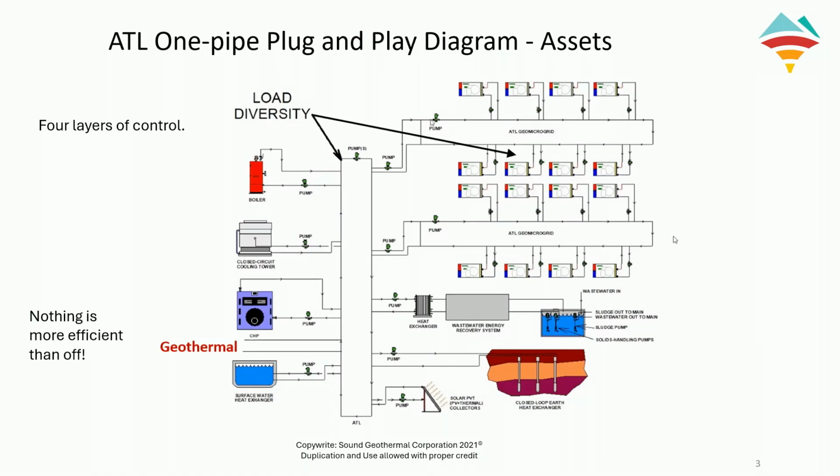open loop sources or sinks, high to mid temperature geothermal resources, CHP waste, and conventional boilers and cooling towers for emergencies or peak loading. This system uses heat pumps and diversity of loads to heat and cool. Borehole and phase change storage is diurnal for load shifting or time of day power reduction, or seasonal for heating and cooling. All sequences are bidirectional, central loop to building or building to central loop.